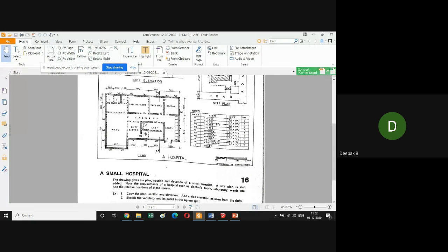So 1 meter also, it will be very congested. It will not be good actually in a public building. So make it 150. If it is a home, you can make it 80 centimeter also. The main door can be made 1 to 1.2 meter width, but the internal toilet doors can be made with a width of 90 centimeter preferably, and minimum 80 centimeter.